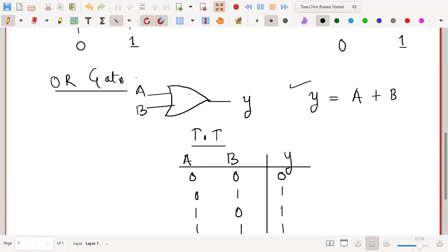Okay, now let us go forward and see what we have here actually. I mean this portion. We are still unaware of this portion, isn't it? So we'll see what is actually inside, which is doing such kind of operations. Okay, so this OR gate is constructed using some diodes or transistors. You can have either only a diode model, or a transistor model, or sometimes you may also have a diode-transistor model as well. Okay? So I will discuss two types of OR gate model. One is the diode model and another one is the transistor model.